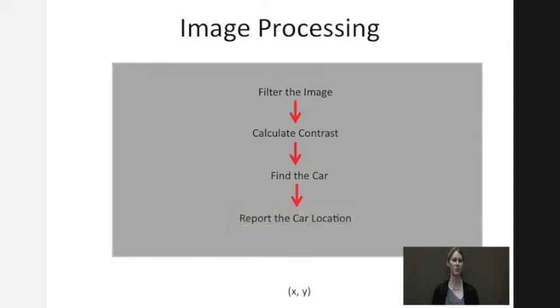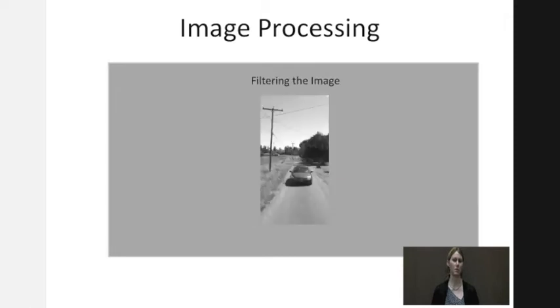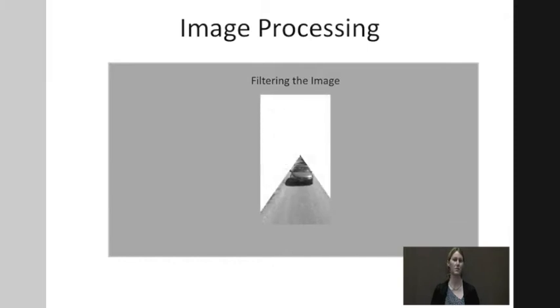This entire process will be pipelined, meaning 2 frames from each of the 4 cameras can be processed at once. The filter, which is calibrated automatically during initial system setup, is run on both images. Essentially, it crops the image so that the only thing left to process is the road. This helps increase performance and decrease power.